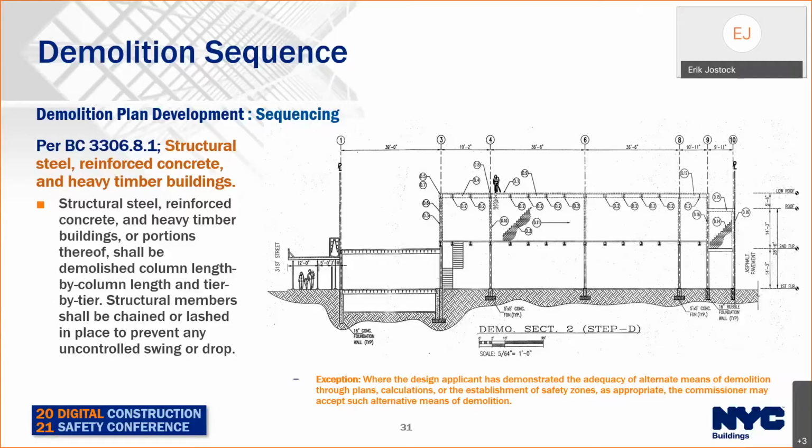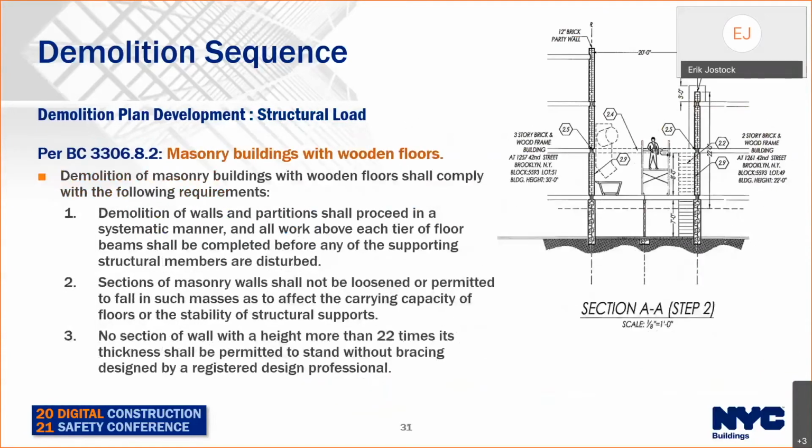Some examples are hinge cutting, dropping beams onto a debris pile or tires. So there are different ways to do this, all submitted with calculations demonstrating that it's not going to exceed the capacity of the floor. Another example of this,